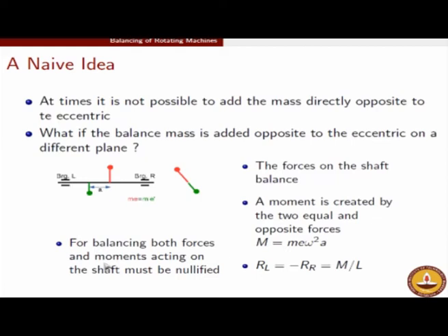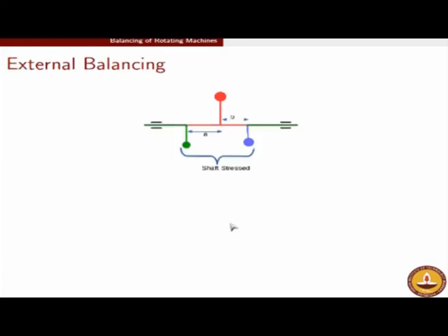If we leave the moments unbalanced, then again the bearing reactions will be induced, and these bearing reactions will be sufficient to induce dynamic fluctuations in response as well as stresses onto our frame, and will cause problems as I narrated a few minutes back.